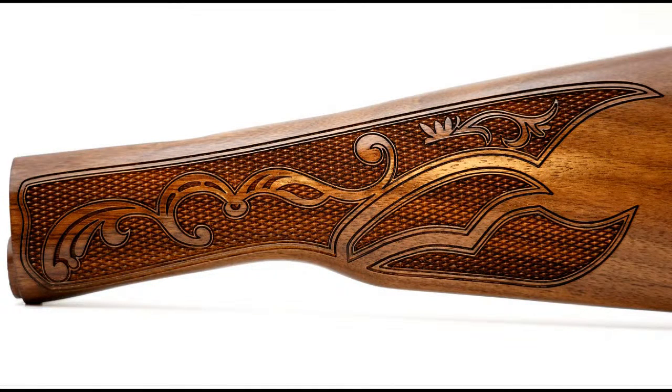So that is the entire process of designing the checkering diamond, duplicating it into a row, using your snap command and your duplication features, and then combining a big array of them into a bitmap so that becomes manageable for your computer, and then using that bitmap to drop into any contoured outline. Whether that contour outline is combined together or not, like this one, the process is the same. And once you've done that and created an array, of course, I've provided you with my array that I did here in our files. And so if you want to use mine and drop it into a contour, you're welcome to use mine or create your own.